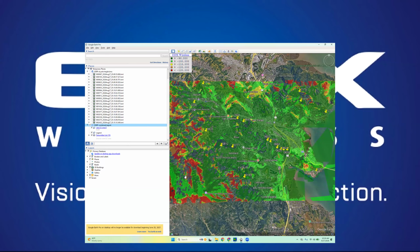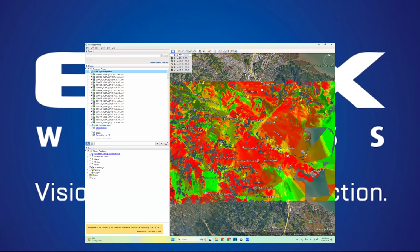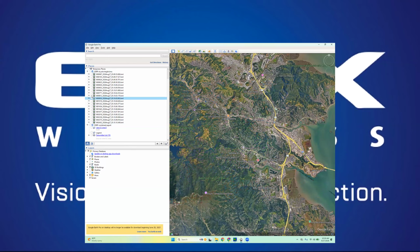But if I ran that study in per sector mode and I export it using that area study queries by point, then I can get another example here where I've got the individual coverage footprint as a separate layer inside of the KMZ. So in this way, I can run that study one time, export this file, and just go ahead and send it on.